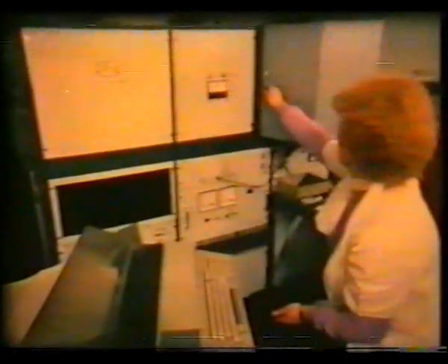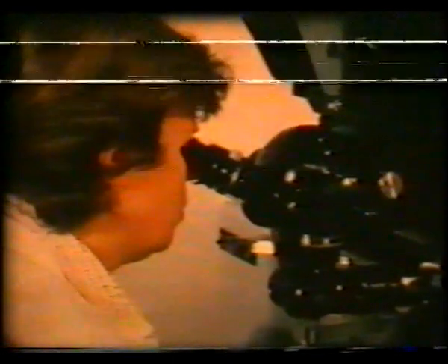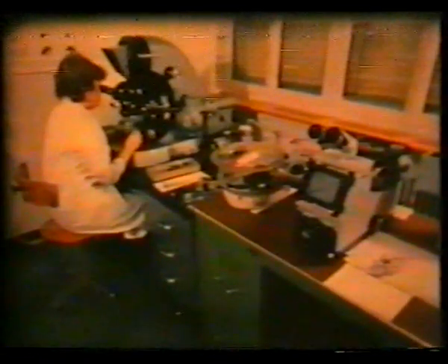To achieve perfect casting quality, we have various testing procedures at our disposal. Spectral analysis permits changes in the alloy to be detected on a continuous basis. Porous sections in the structure of a casting become visible in the X-ray test. Purity is analyzed under the microscope. Our metallurgists and their modern testing equipment are also at the disposal of our customers.